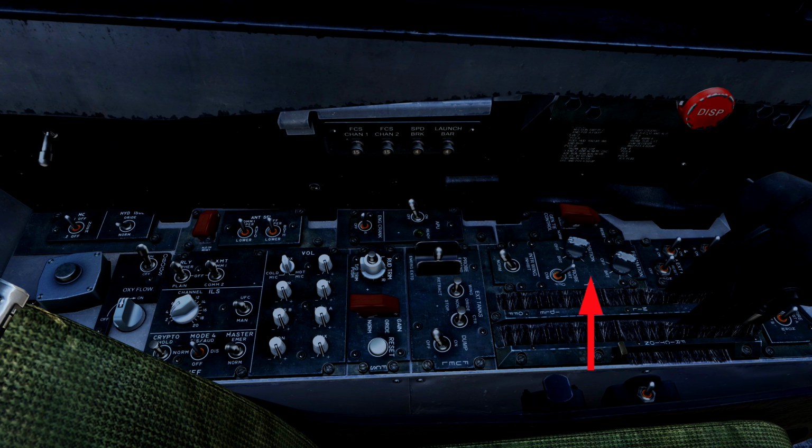And above that, we have the exterior light controls, and this includes a strobe switch for 2 red strobe lights, the position lights, and the formation lights, or the slime lights. And outboard of the external light panel is the generator tie switch, and this allows the pilot to override the AC bus isolation circuit, but in all likelihood you'll probably never have to touch the switch.